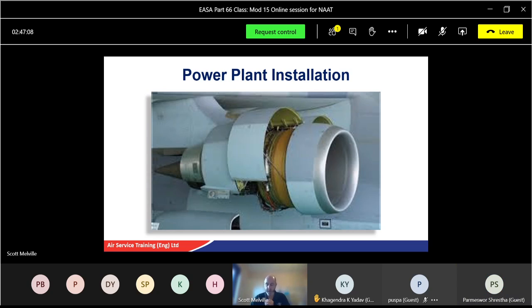What's the typical epicyclic gear ratio formula? Typical one. Driven gear over driven gear plus fixed gear. Yeah, it can be roundabout. For the purpose of examinations, though, just the one in your book is fine. They won't give you that one and then the flip version, because that means the same thing. You'll just get an inverse number. What's bigger, your crankshaft or the drive shaft gear?